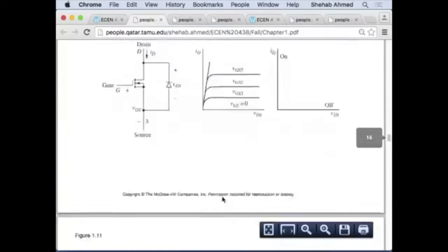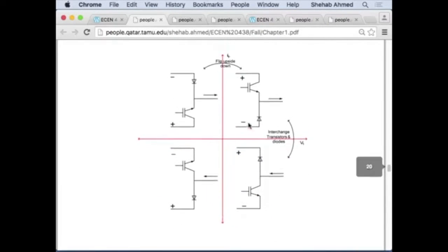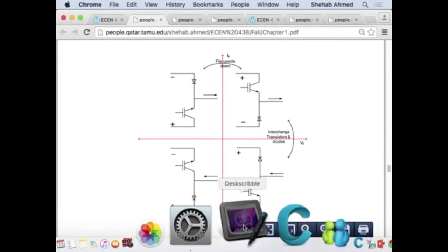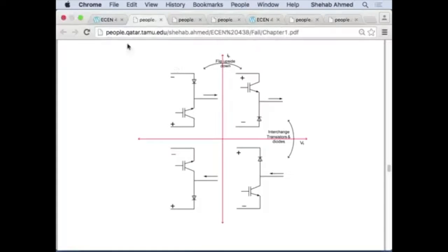the table that we had with how to select switch architecture, right? I have current here, positive, and current here, negative. Voltage is only in one polarity. My voltage here does not change polarity, it is always in the same polarity. My current is changing, either positive or negative. So I have to consider this selection of devices as well as this selection of devices.